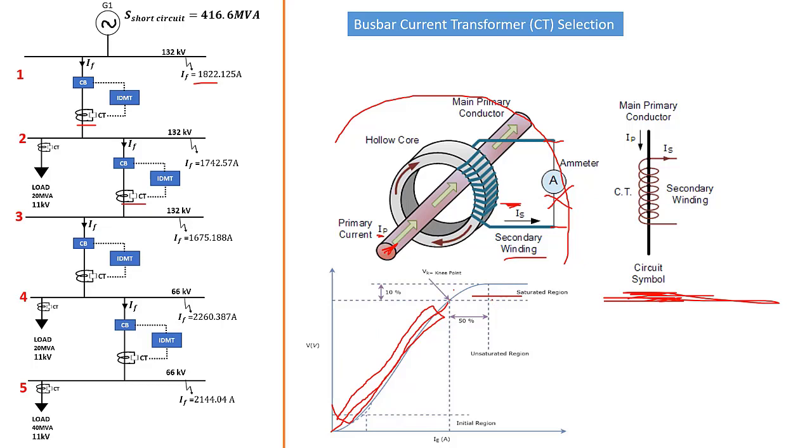Why is it a danger zone? Because it doesn't matter what that current is now. The output will no longer give an accurate representation. We could be having 100 million amps there. This secondary IS will not tell us what exactly that current is. So protection is lost. You don't have your protection anymore. So that's what we call the saturation region. When the current transformer gets to that point, it becomes useless because it's not protecting anymore.